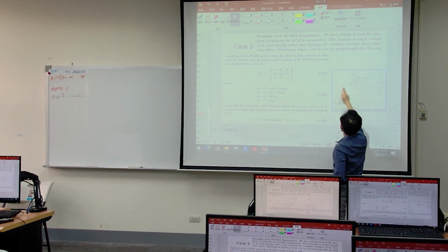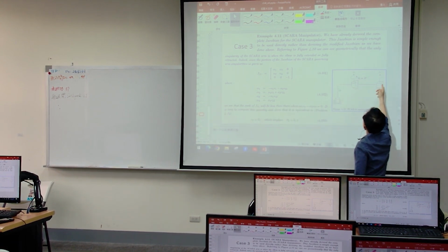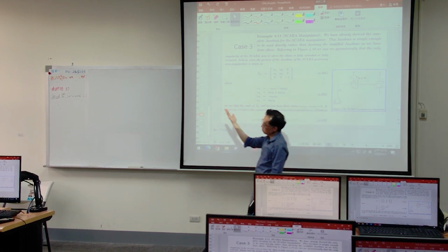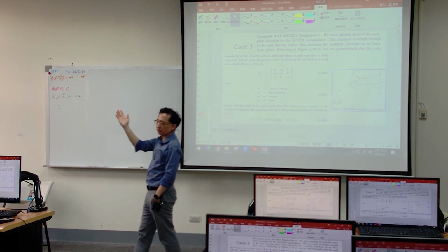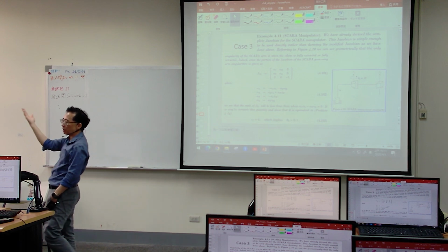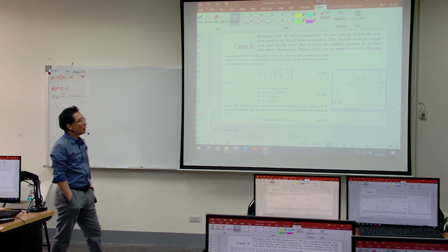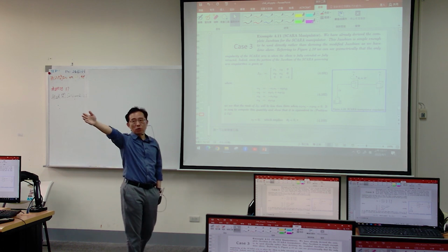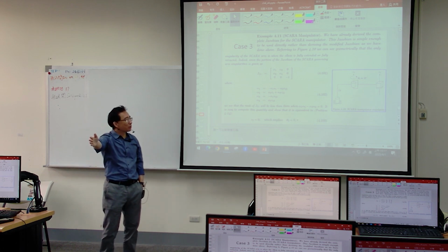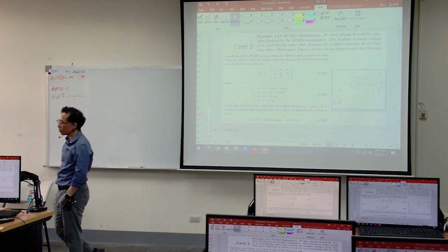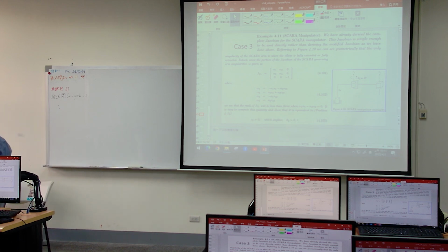0 and 180. Then the Z2 position is different. For me, the position is different, so how come it's a singularity? Yes, but it is a singularity situation because it is straight aligned with joint 2. So this is another singularity example for SCARA.